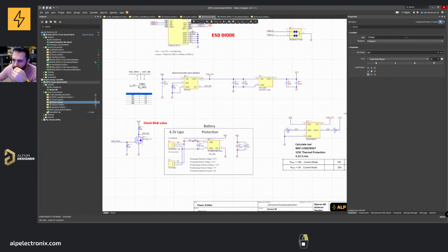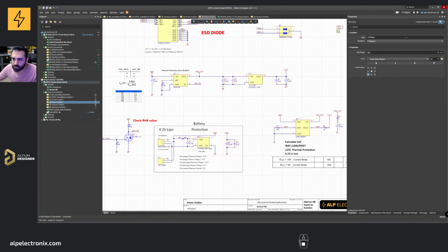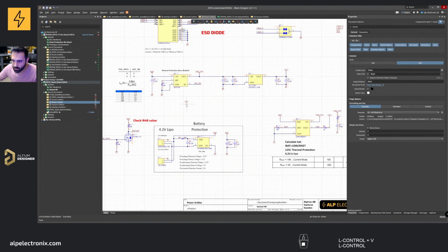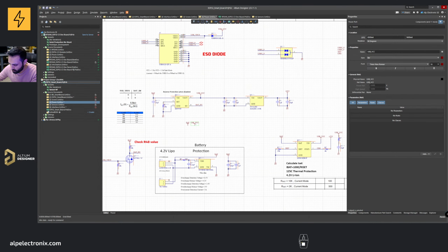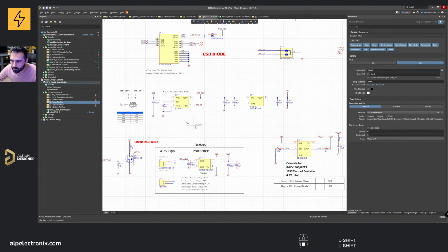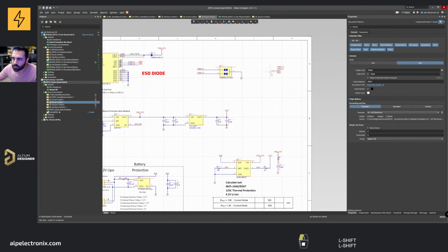Power. Yeah. Yep. So this is the battery output. And USB VCC, because we can supply voltage from outside. Oh, if we want to supply not USB VCC, we need to supply to USB VBUS, and then USB VBUS needs to go here. Yes.